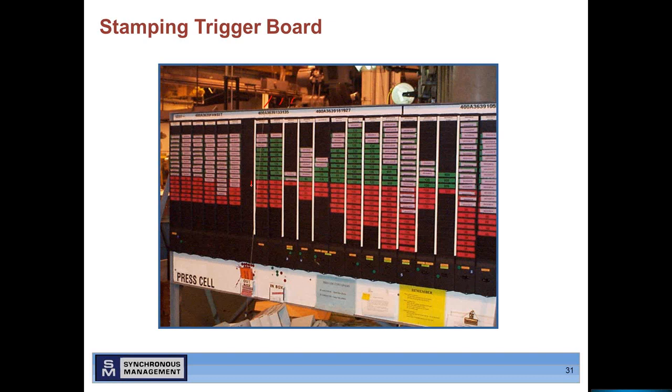They calculate for each item an order point, which is the red cards, and the order quantity, EPEI, which is the green cards. And the pink cards here are the Kanban cards themselves. So you can see on this item, for example, the supermarket is full, all the Kanban cards are with material. And on this item, we're almost out. We have two Kanbans on the board, there's only one left. So we know we have less than a container left in the supermarket.